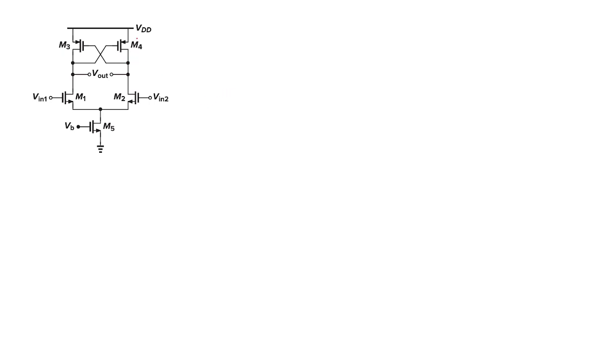Here the load is a cross-coupled PMOS load. We have to first find the impedance offered by this structure, then our problem will be easy, right? So from points X and Y, we find the output impedance looking from here. Let's draw the circuit.